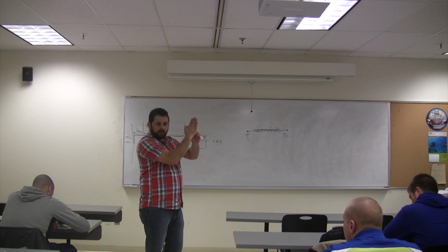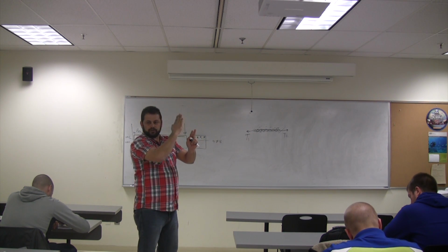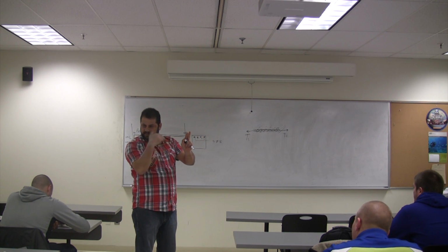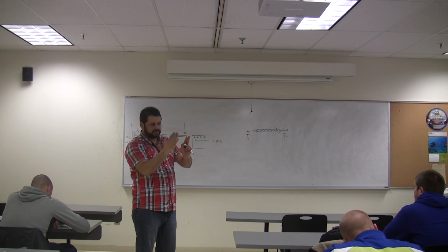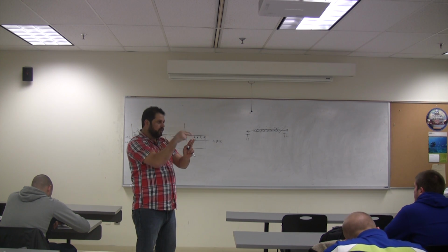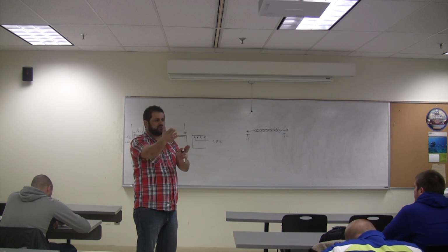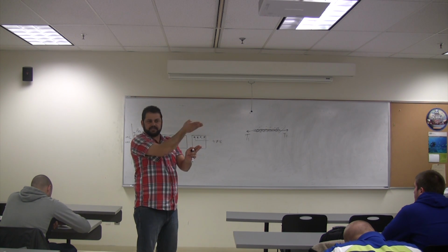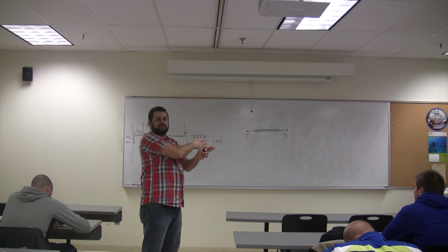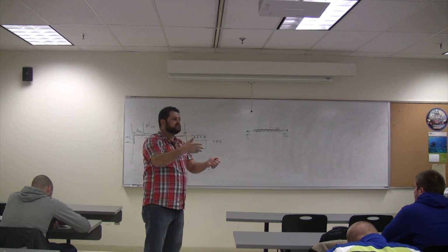At this point, no, you can terminate 2 bars. Cut-off point, termination of bars. When 2 are enough, why do you need more? The moment diagram, the moment is decreasing. Why would you need to continue the 4 all the way? This is what you see, guys, realistic.